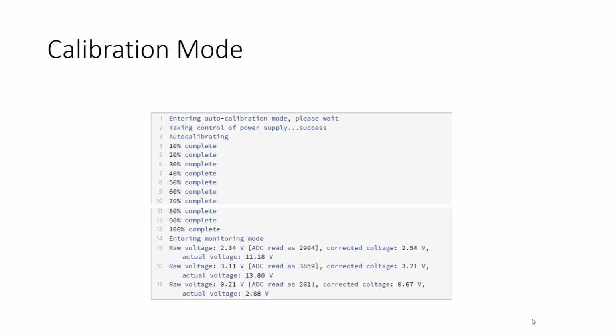You read a 12-bit value, which is between 0 and 4095. Then you divide it by 4096, and that is the ratio that you multiply by 3.3 volts to get this. So this is a proportion of the 3.3 volts as indicated by the 12-bit value from the ADC. Okay, so that's the raw.